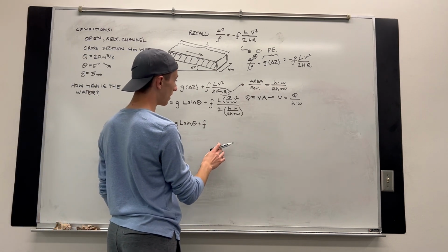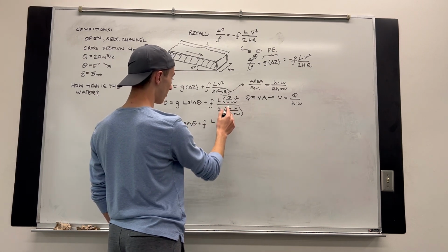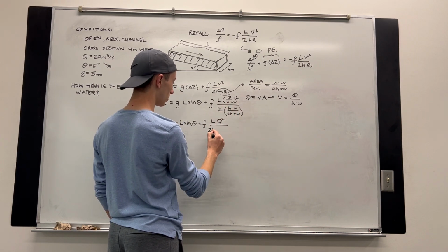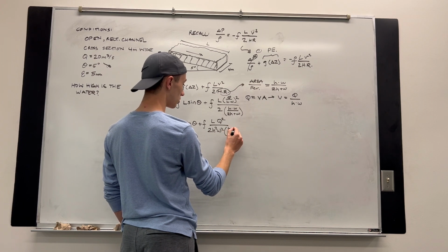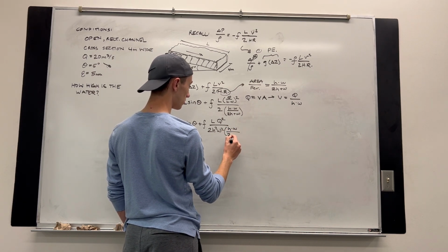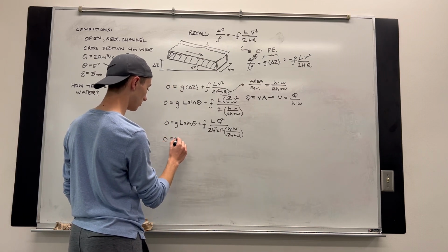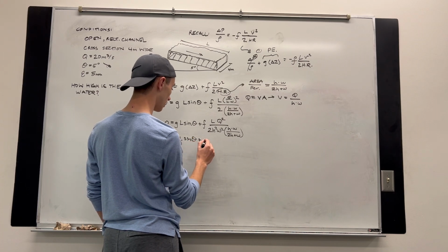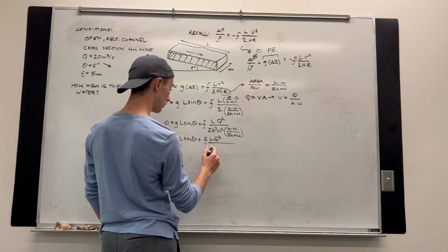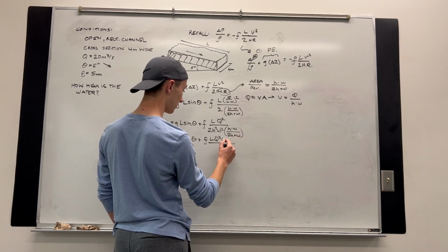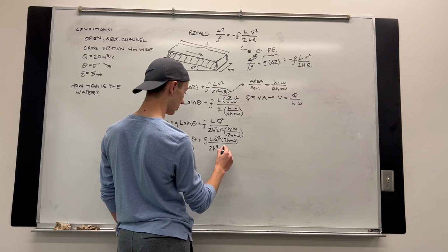So we have L Q squared, divided by 2 times HW squared, times H times W over 2H plus W. And rewrite, keep going down here: g L sine theta plus f L Q squared over, moving this back up to the top, 2H plus W up here, and on the bottom we have what would appear to be 2H cubed W cubed.